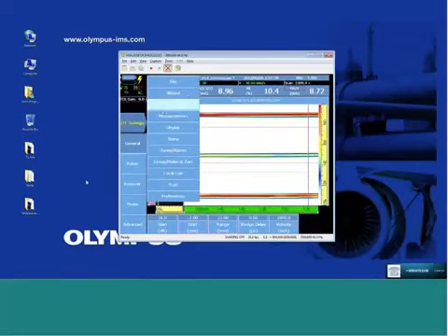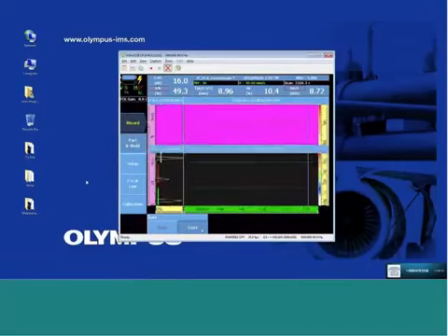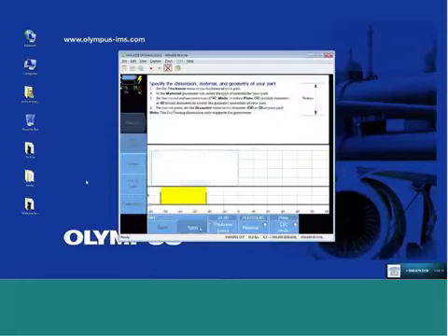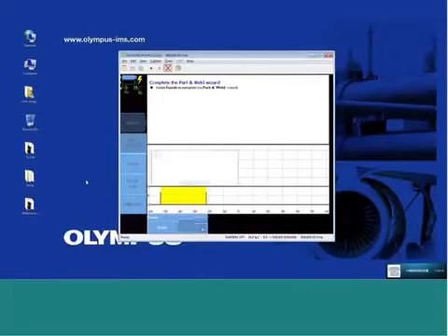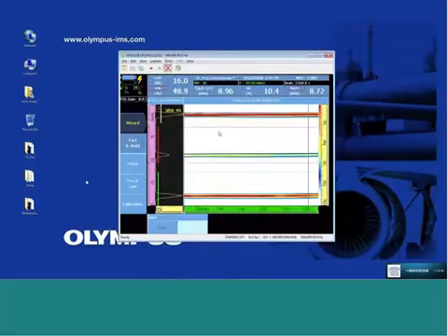Under the wizard, the part and weld wizard is completed in this application only relevant for the thickness of the material being inspected. No weld is used in this application. When we set the thickness and the velocity and the component under the part and weld, this is relevant to all groups. The setup is relative to individual groups.